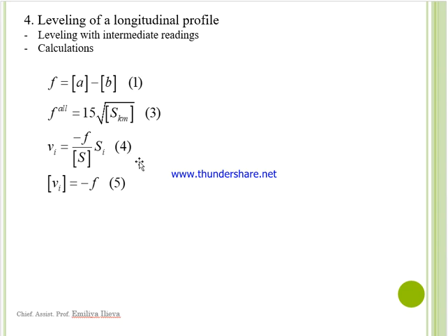You know all of these equations from the previous semester. I think in exercise 4 we have measured this kind of loop leveling line, and for verification, the sum of all of the corrections must be the misclosure with opposite sign.